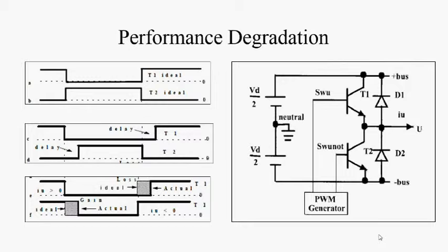Performance of the inverter is being degraded due to many factors, and the dead time is one of them. Since the practically available switching devices are non-ideal, there's a finite turn on and turn off times. Hence, in order to avoid a shoot through in the DC link, the turning on device is being delayed by a finite time amount. This delay is known as the dead time. This very delay causes serious output distortions and results in harmonics.